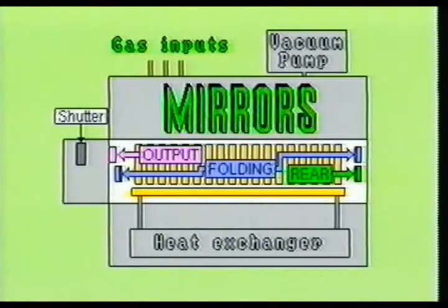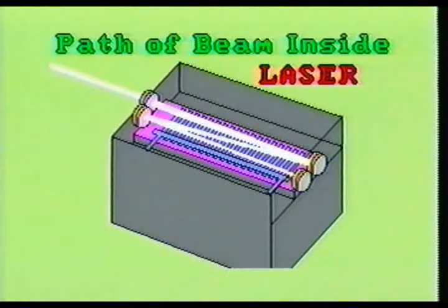The CO2 gas laser will generally contain a series of mirrors in the optical cavity. There will be a rear mirror, 2 or more folding mirrors, and an output mirror. The output mirror is often referred to as an output coupler. The rear mirror and the folding mirrors will be 100% reflective, while the output coupling optic will be about 96% reflective. Notice that the beam originates off the rear mirror, then reflects off the 2 folding mirrors, then exits the output coupler. The purpose of the folding mirrors is to force the photons to pass through the excited gas molecules, thereby increasing the strength of the laser beam.